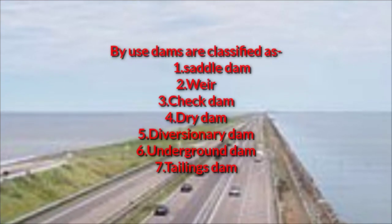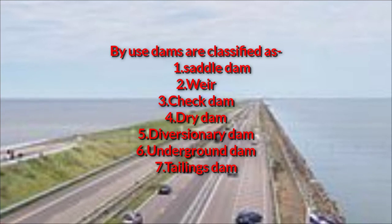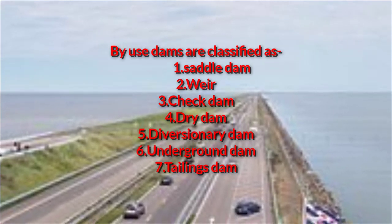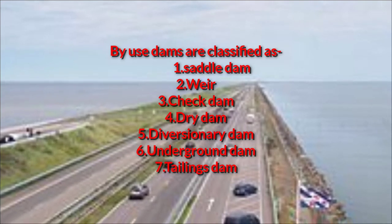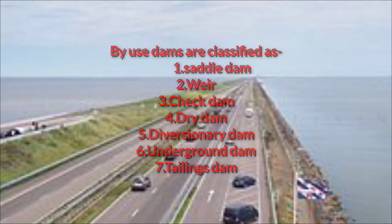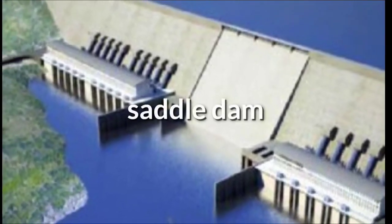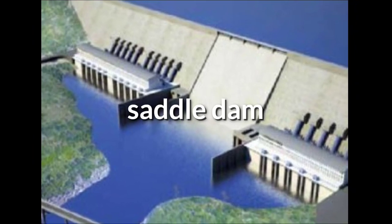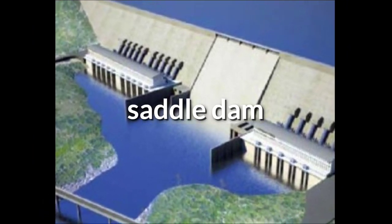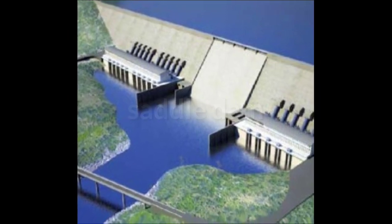Again, by use, dams are classified as saddle dams, weirs, check dams, dry dams, diversionary dams, underground dams and tailing dams. A saddle dam is an auxiliary dam constructed to confine the reservoir created by the primary dam, either to permit a higher water elevation and storage or to limit the extent of the reservoir for increased efficiency.